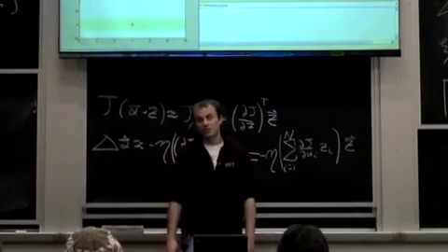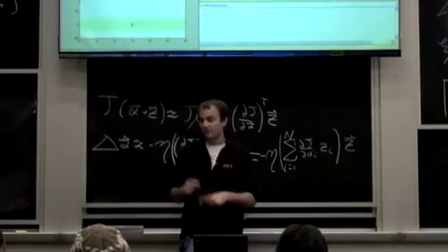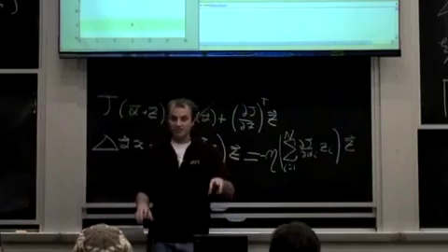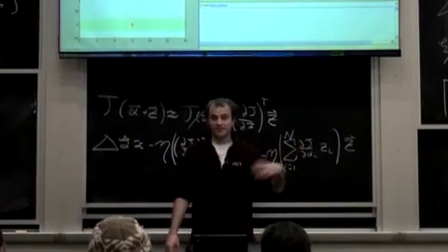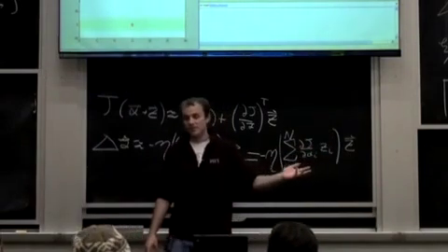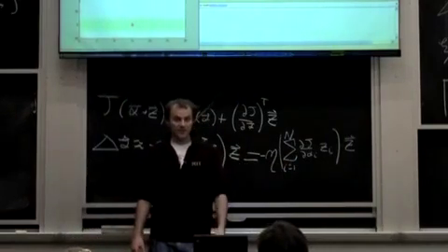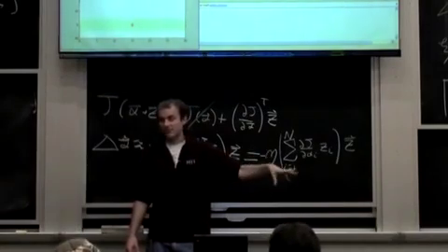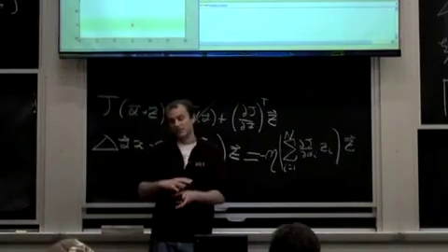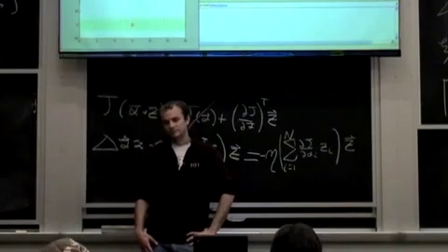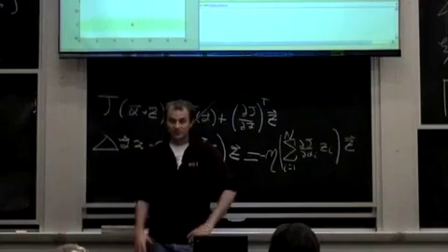And that can be a win when you have a lot of parameters that aren't well correlated. Imagine you had a feedback policy where a parameter is active in a certain state, like if I was at -2 to -5, I do this. And let's say I never get there, then that parameter has nothing to do with how well I perform. If you know that, there's something called an eligibility trace you can track, and you can not update that parameter. There's no reason to be fooling around with that parameter when it's not affecting your output. And we have a more careful way of shaping this Gaussian to learn faster, and also a completely different kind of sampling.